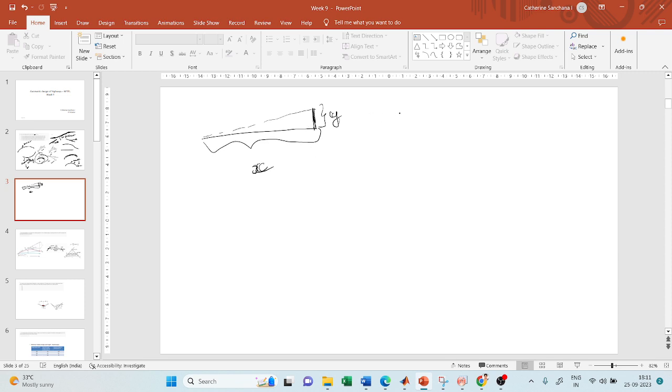Now, how will you define a grade? Grade is the rise in the vertical direction, which is y, divided by how much distance you have traveled in the horizontal direction, which is x. Since both have units of meters, grade is actually unitless. It is just a fraction. But mostly we will express this grade as a percentage, or you will also call it as a 1 by n.